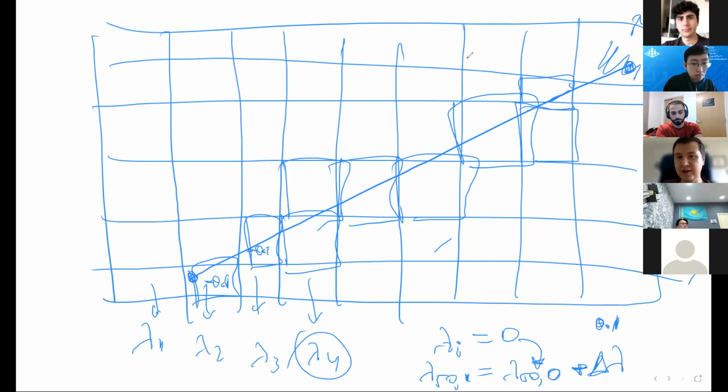over here. Okay, so if we think of the larger values being dark and more negative values being light, we're going to see our matrix that represents the map get darker in the places where the LiDAR hits obstacles, and get brighter or more negative in places where the LiDAR rays indicate that the environment is free. Okay, so this is now what we're doing. Instead of just looking for the points, we're actually increasing or decreasing the values in these cells.